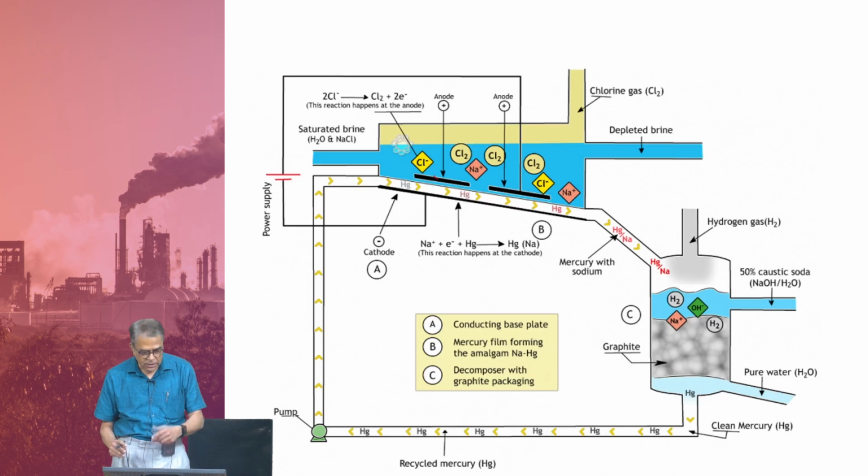So, in a separate piece of equipment, you take that and add water, pure water, because that water relates to the caustic soda's own product specification, plus you do not want any other impurity finally going into the product. In this case, because this is a different piece of equipment, unlike here where there is a thin flow without the film getting disturbed, you violently make conditions so that droplet to droplet they react.